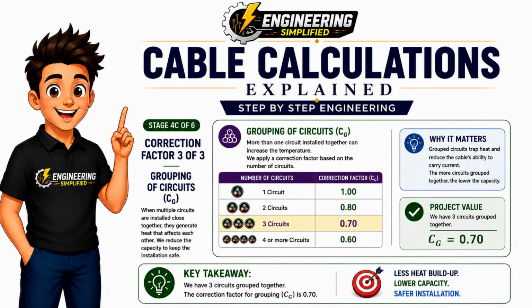The final correction factor is grouping. When several circuits are installed close together, they warm each other up. This additional heat reduces each cable's ability to carry current safely. In our example, 3 circuits are grouped together. Looking at the grouping factor table, this gives us a correction factor of 0.70. This is the largest reduction we've seen so far and has a significant effect on the cable's allowable current.